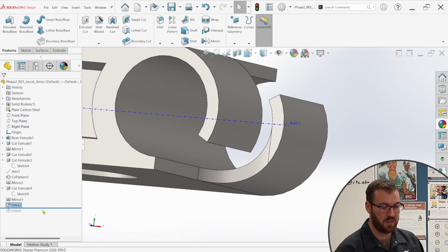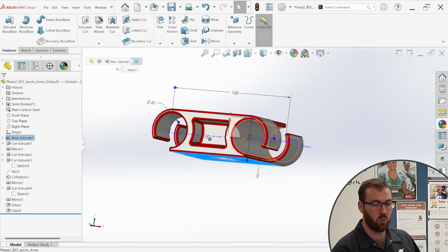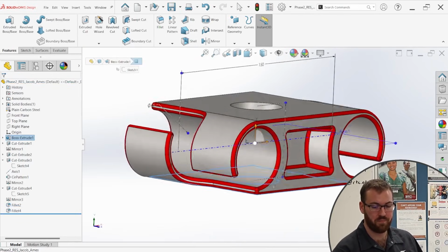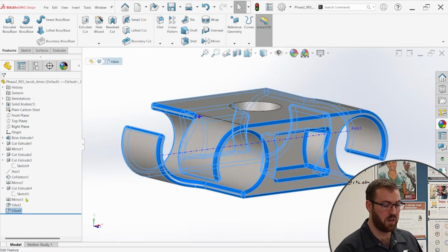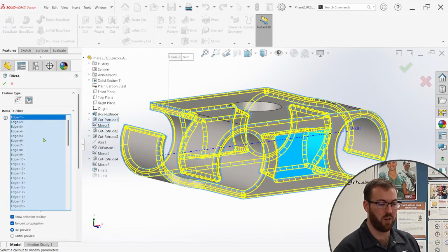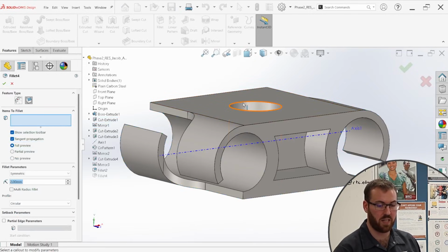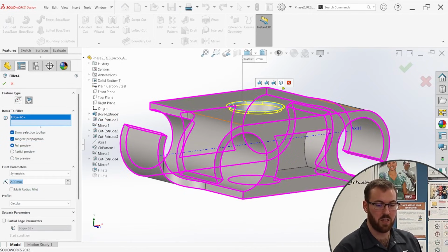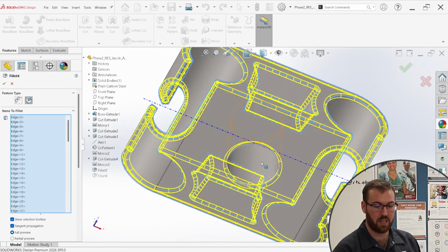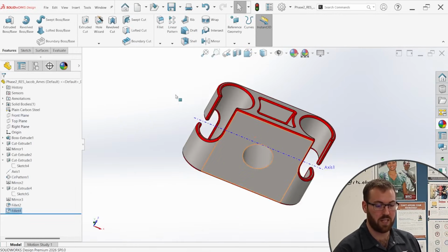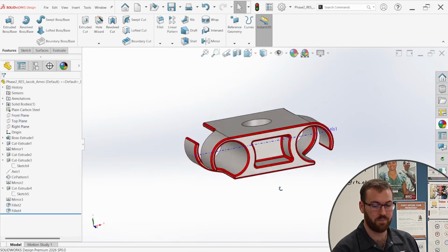And then last but not least, here we would actually be able to roll forward and bring our old fillets back. Likely it would need some adjustment because there's going to be a lot of additional edges, but using our exact same strategy as before, we could very easily clear all these selections, choose an edge, select all edges, and just like we did, deselect the two edges that are not included, and there you go. That's a fillet for every single edge.